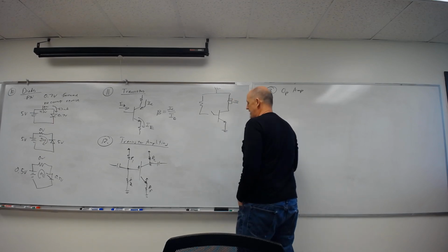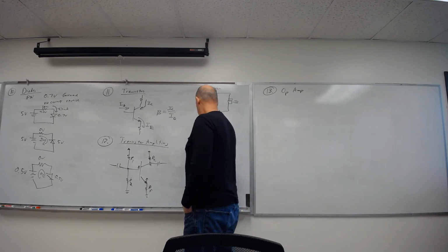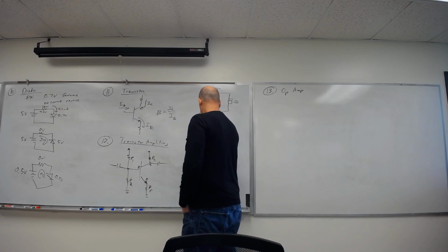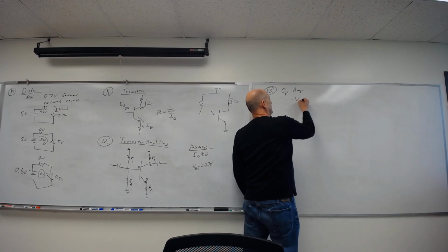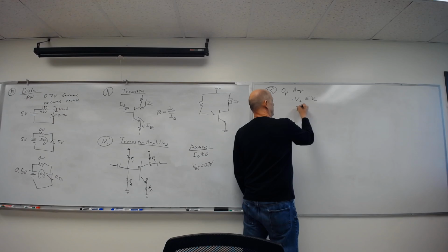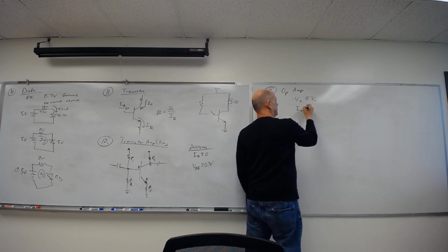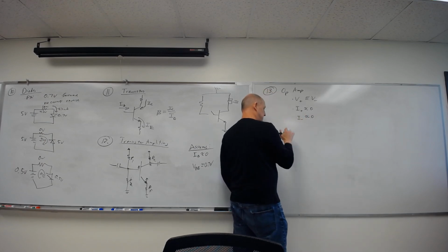So, okay, a couple things here. Remember, we assumed the base current is approximately 0, and we assumed the base to emitter voltage is 0.7 volts. Those are assumptions we made. And I list those over and over and over when I go through these. Op amps, what are my assumptions there? The two inputs are identical, and the input currents are 0.